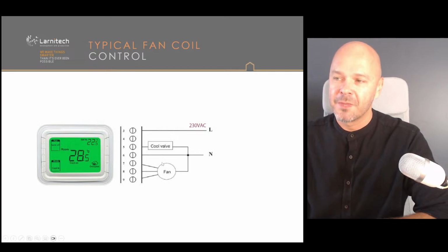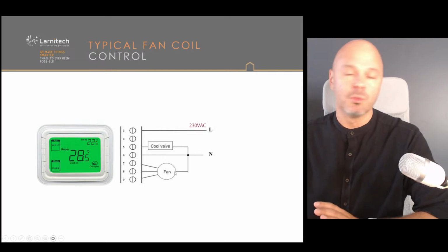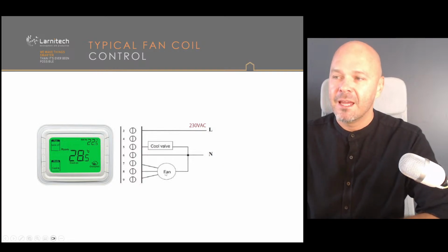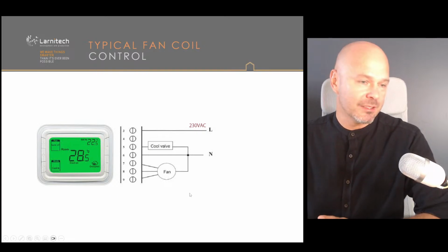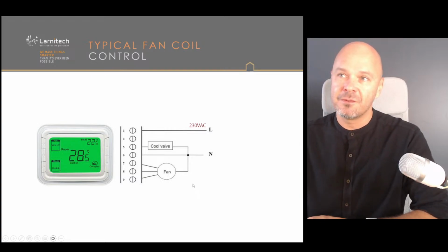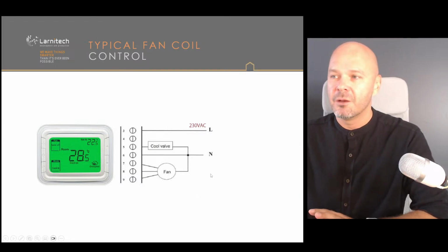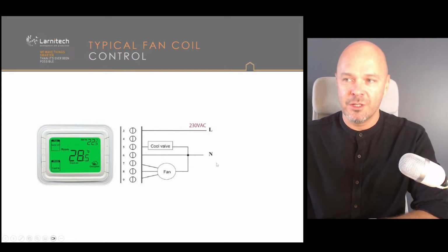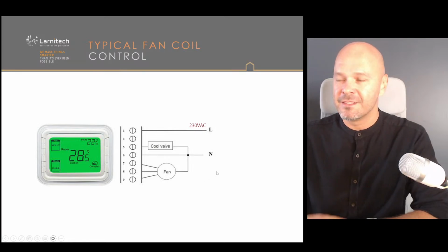The fan coil has cool water, so you need to turn on the valve and water comes in. And then you control 3 fan speeds: low, medium, and high. This is the connection for a typical thermostat, which you will have in almost every home with district cooling, which is very popular in the UAE, at least in Dubai and Abu Dhabi.